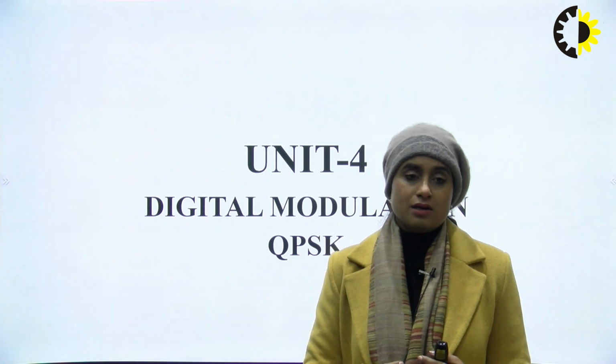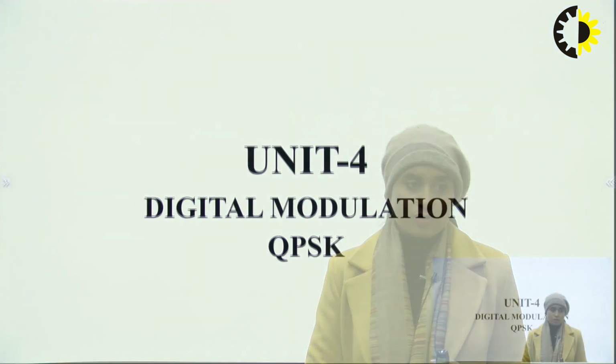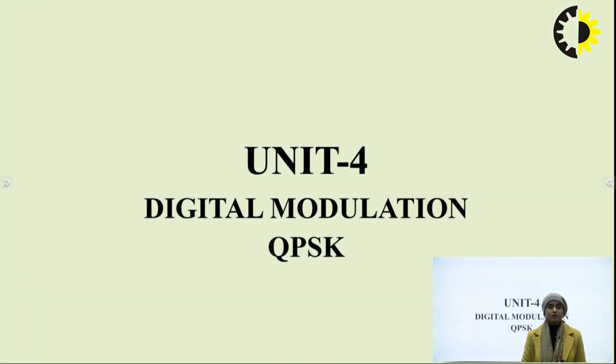Here, the basic forms of digital modulation schemes that we have studied so far are ASK, FSK, and PSK, and QPSK is a variant of PSK. In ASK, the amplitude of the high frequency carrier wave is varied with respect to the input binary bits, in FSK, the frequency of the carrier wave is varied, and in PSK, the phase of the carrier wave is varied with respect to the input binary bits.